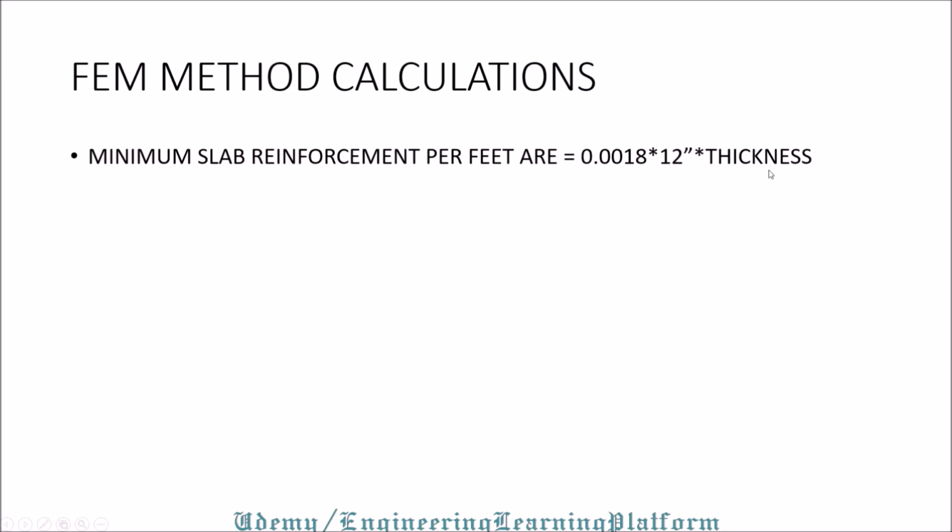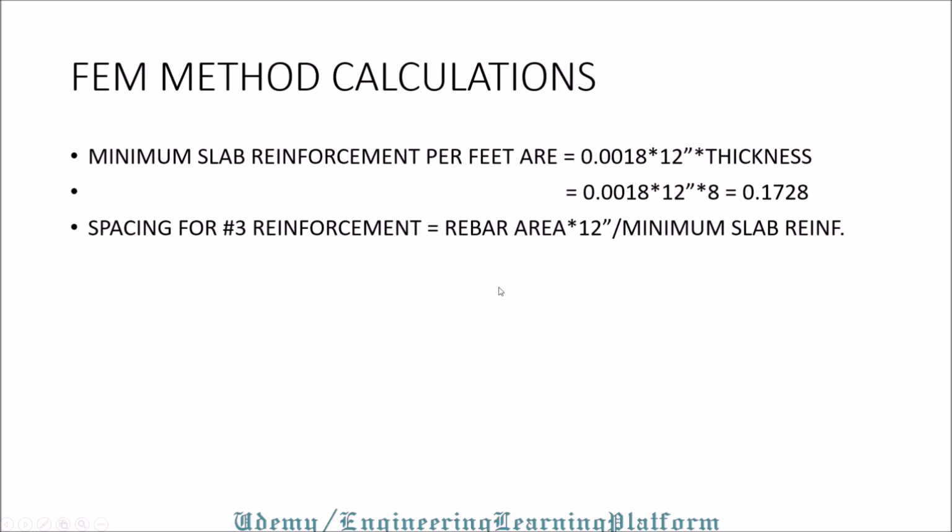The thickness of the slab is 8 inches, so our minimum reinforcement to be provided per foot is 0.1728 inch square.